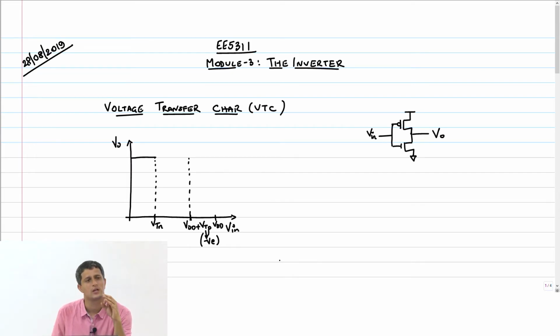And remember, what is our constraint? IDSN is equal to minus IDSP. This is not an artificial constraint that we are imposing. It happens because the two transistors are in series, and therefore the series currents have to be the same, which means V out will adjust itself so that these two currents are always the same, for all input combinations. To remind you, this is the drain for the NMOS, this is the drain for the PMOS, and the source is fixed at VDD.